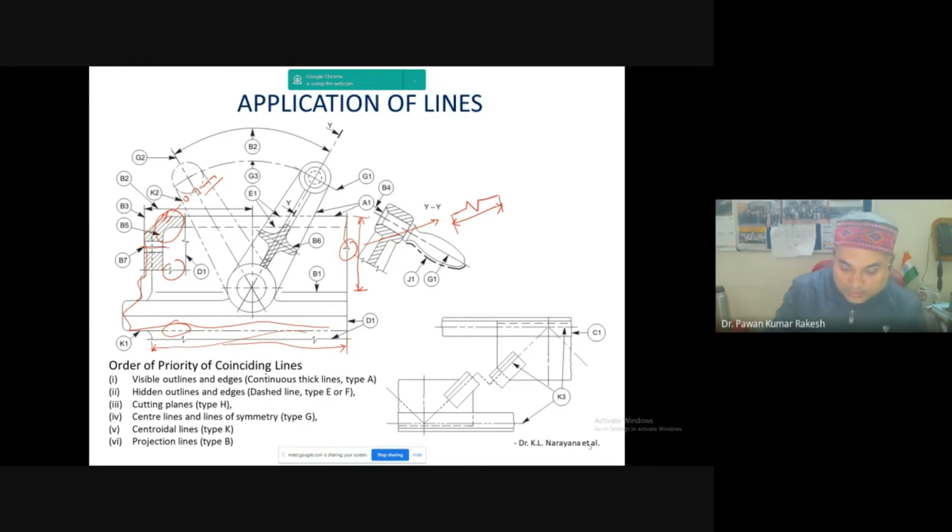You can see the hidden line. This position is here now, right? This is the actual position of this object, and we are showing this part. Suppose this is the piston part, so the piston will move from this side to this side. In that case you can put the hidden line within the center lines, and with hidden lines they show that this part is movable and will come to the second stage at this position, or in the third position, so you can also draw it.